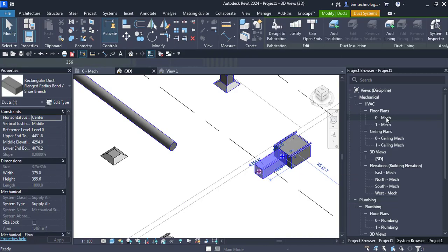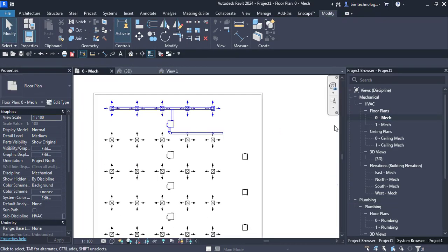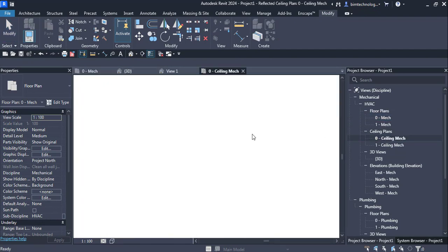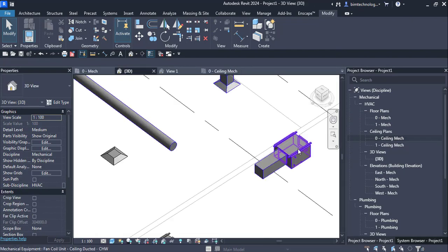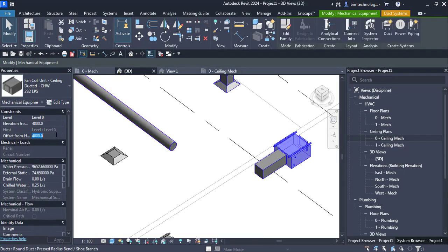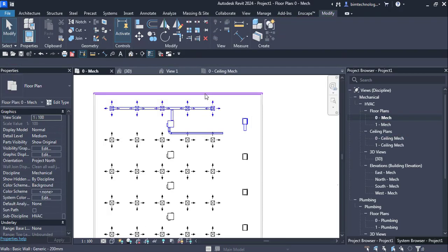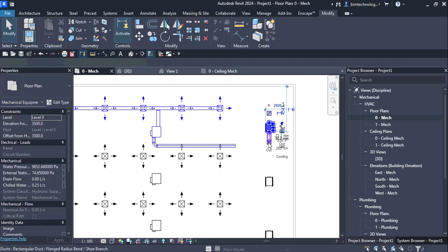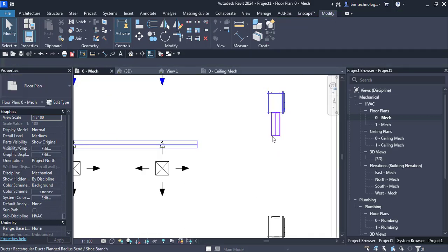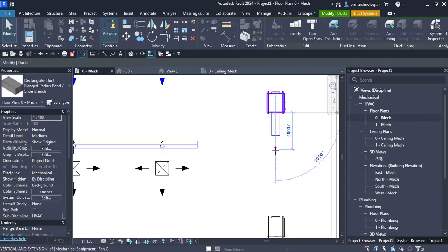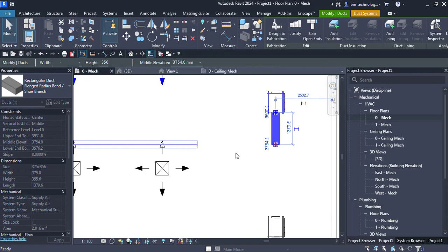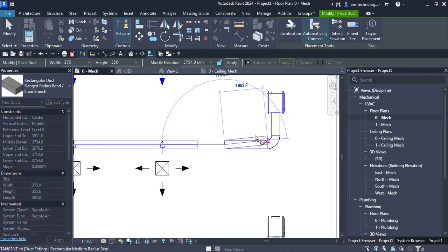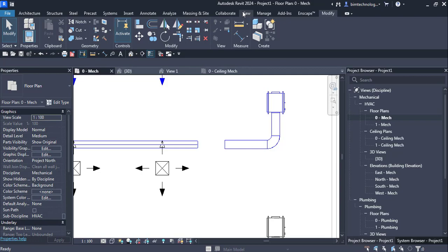and then what you can do is bring this here, or let's say you can go to the ceiling plan and look into it, or into the 3D view, because this is something that you can bring down. Let's say bring it to 3500 here, and in the plan view it will be visible here. So what you can do is bring this duct to a part which is in parallel to this one, and then try to draw another duct